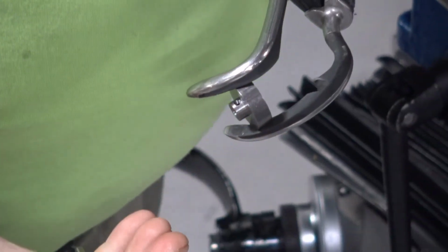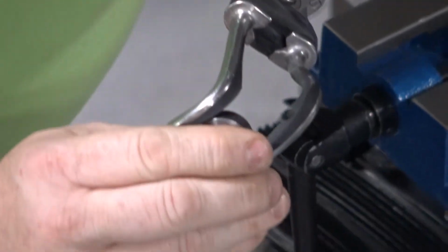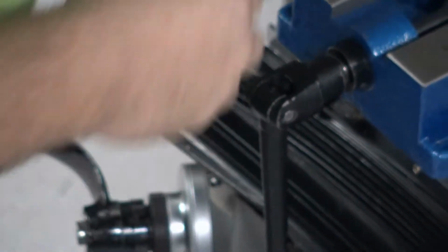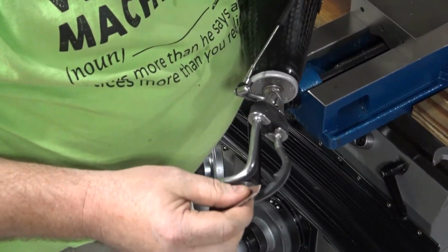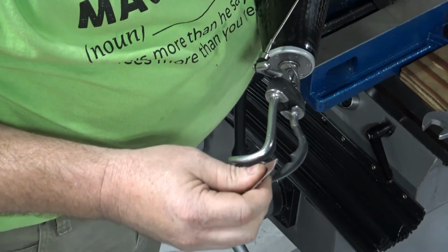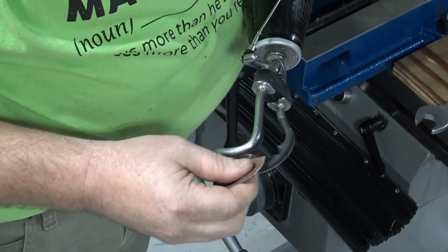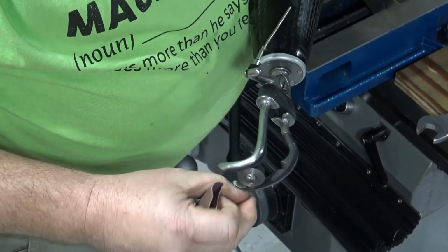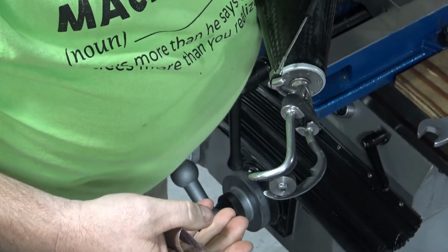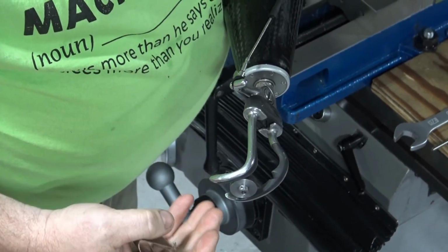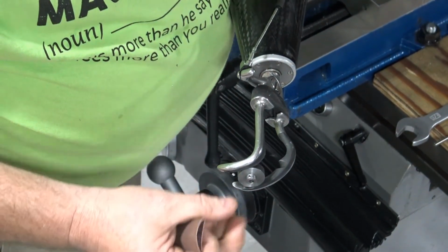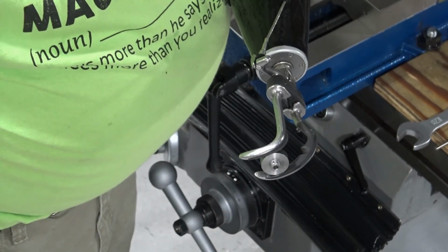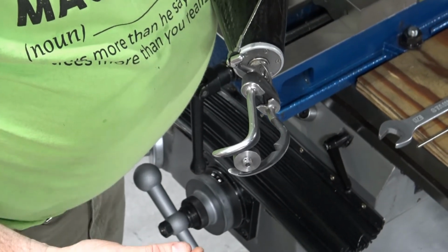Once we have those burrs cleaned out, if you'd like, you can go back and take some emery cloth across that top surface to get the burrs off the top. Now I don't get too worked up over the burrs across the top, because when it's assembled in the air engine, it's not actually a surface that you're going to be able to get your fingers to and potentially cut somebody.